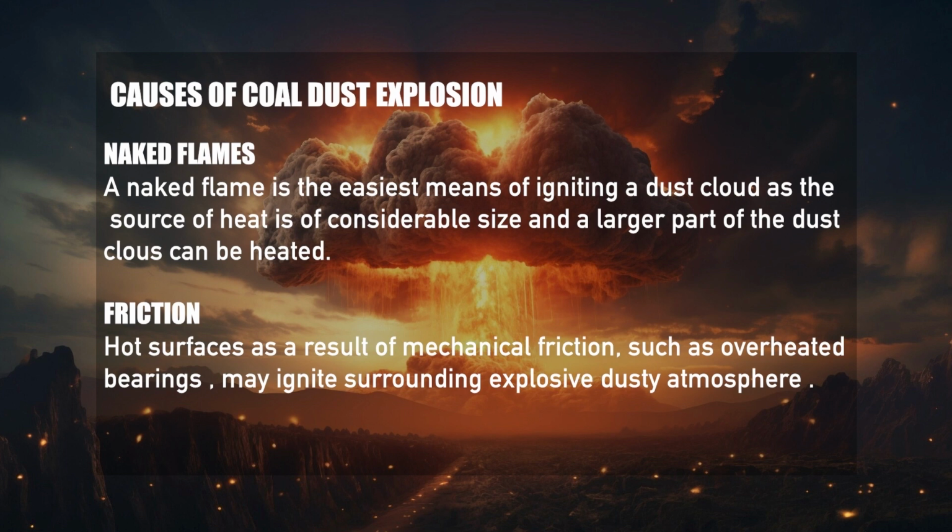And again, coming to friction. Hot surfaces as a result of mechanical friction, such as overheated bearings, may ignite the surrounding explosive dusty atmosphere. Again, friction during rope haulage, fast movement of belt and rubbing of belt against steel prop or timber prop inside underground mines may also cause heating and finally ignition of coal dust, which leads to a coal dust explosion.